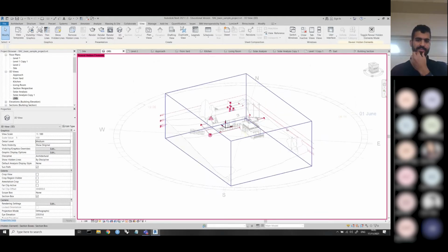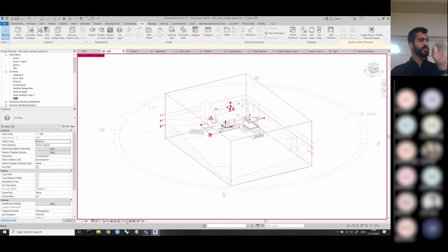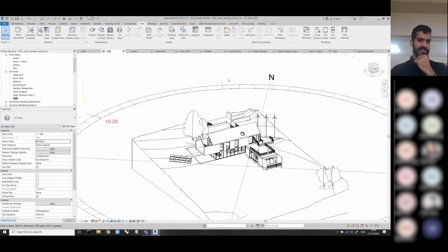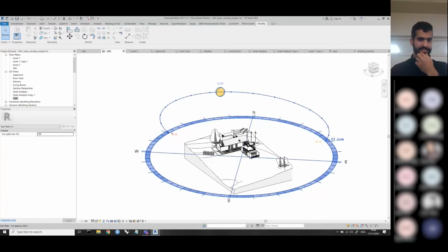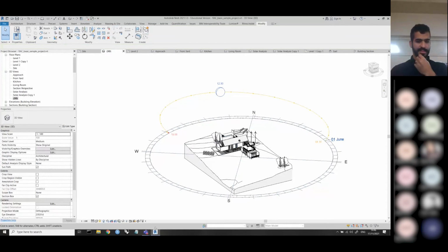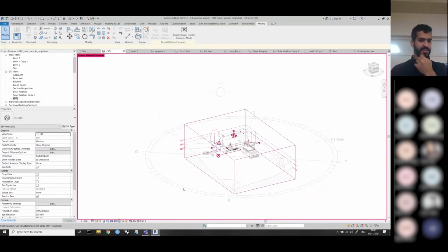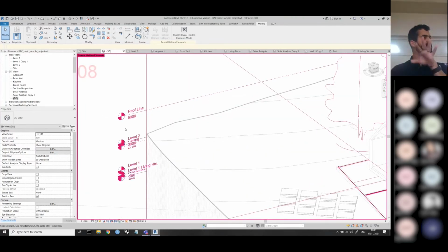So again, this is very useful to show over here. This one over here, where it has the lamp, it shows you the hidden geometry. So in this view, I can go over here and hide. Let's say this is another information pack I want to communicate. I can go hide over here on modify. I can't hide this, but maybe I want to hide the tree. Hide elements. And then if I go here, it shows me that it was hidden. So you can see here in 3D, you also have the levels, and it's hidden in this specific view.